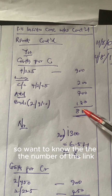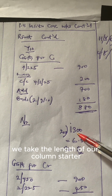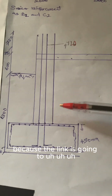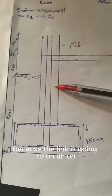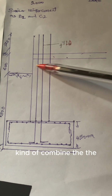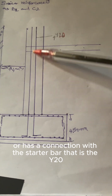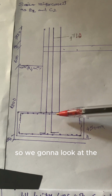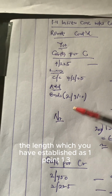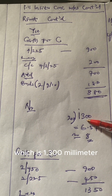So we want to know the number of this link. How do we establish the number of the link? We take the length of our column starter, which we have established already, because the link is going to combine, or has a connection with the starter bar, that's the Y20. So we're going to look at the length which we have established as 1.3, which is 1300 millimeter.